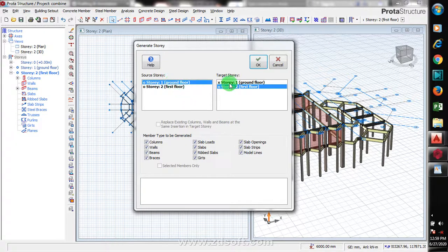Understand this: I will generate both the beam and the wall. But just in case you want to change the kind of beam that will be on your roof, you can as well just trace the axis and then specify the size of your beam. You can actually do all of that.